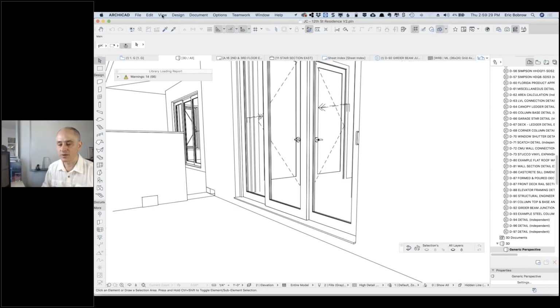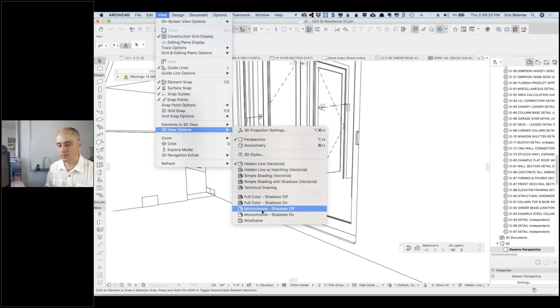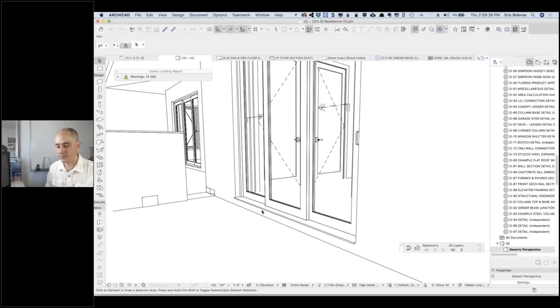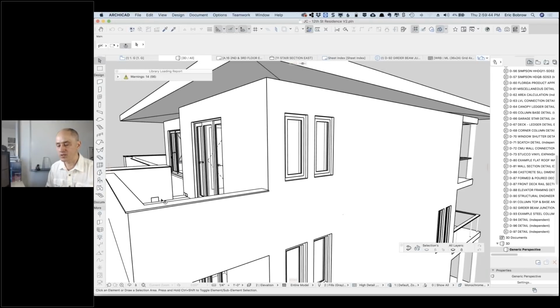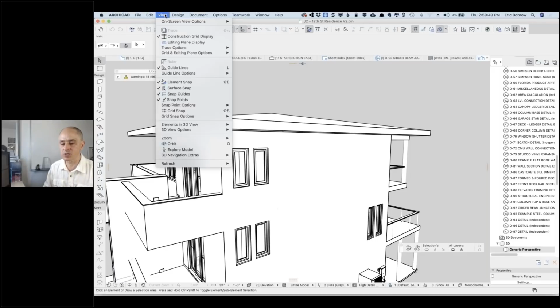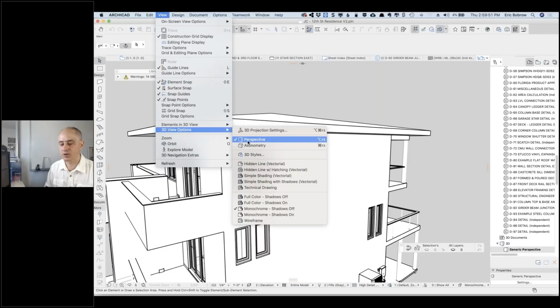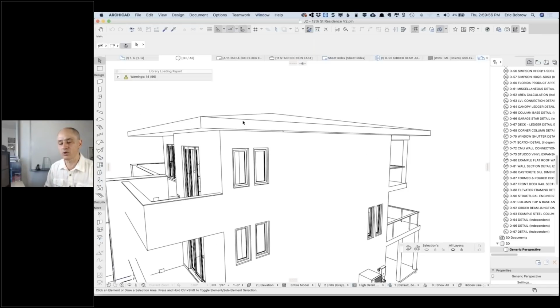Whereas if I'm in the monochrome one here, it may or may not have the same crispness. You can see some little artifacts in places, because OpenGL is a quick approximation. But you may want to just see how you prefer the hidden line one. Now, the hidden line takes longer to do, but it is generally going to be a crisper result.